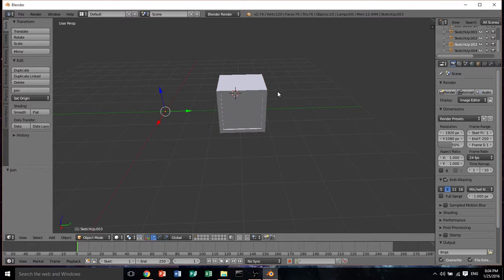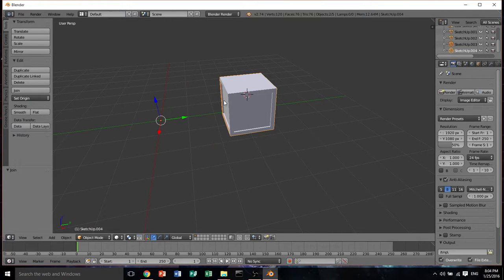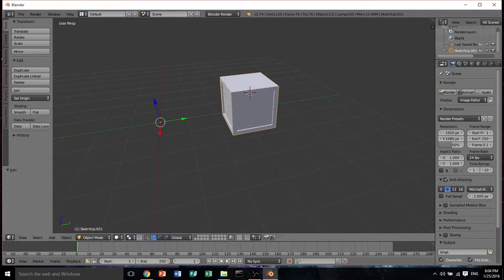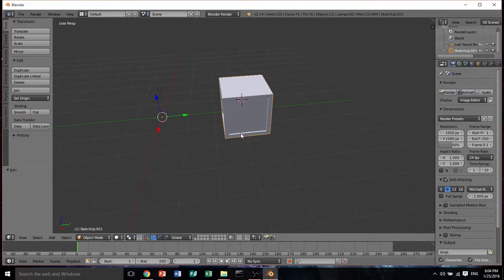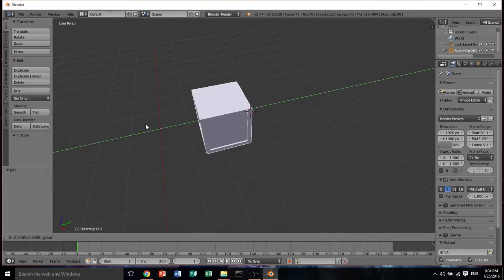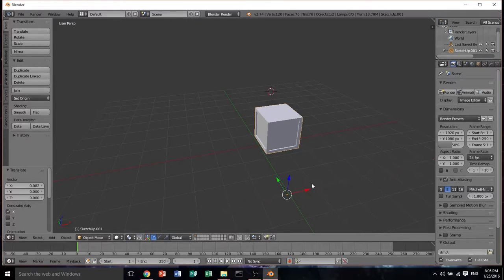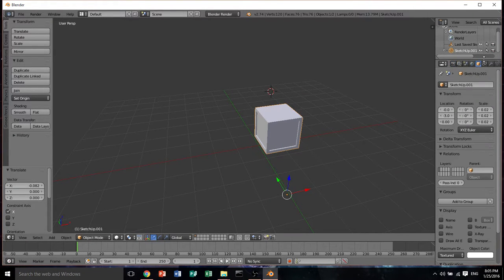So we've got that. Let's keep adding more of these different parts. This can be a little bit tedious, and sometimes it can be tricky finding how to do that. So you can either click through the hierarchy, or you can click on the different sides right there. Now, let's move this over maybe to the center, so when it spawns, it'll work pretty good. Actually, we're going to click on this cube underneath the hierarchy, click on location, type in 0 for each different section right here. So just click on it, type 0, hit enter.